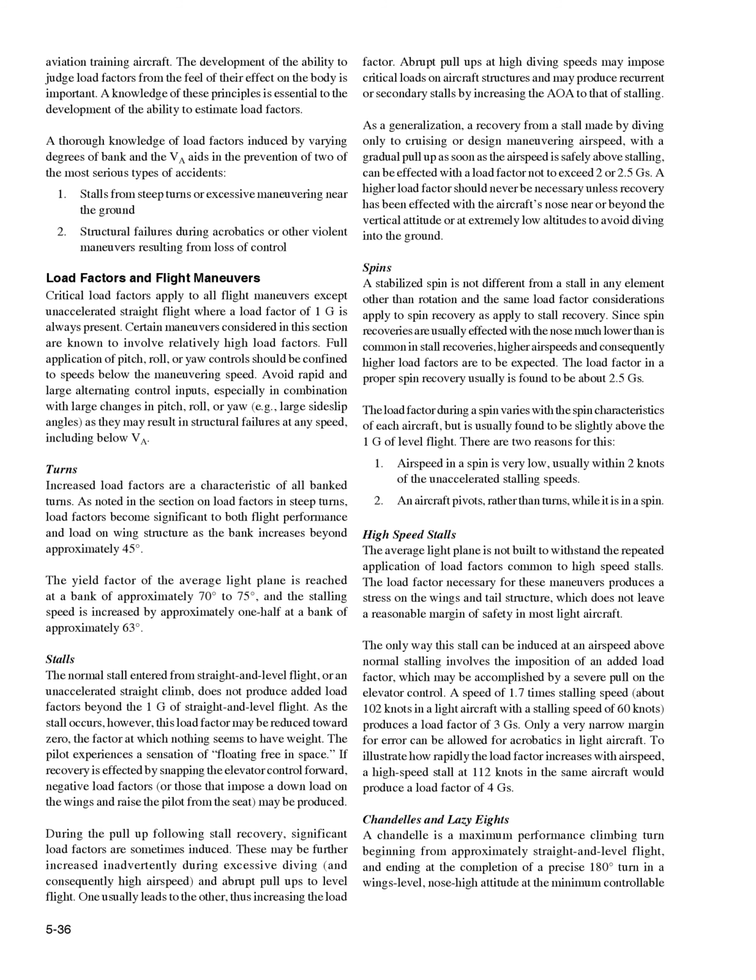A speed of 1.7 times stalling speed, about 102 knots in a light aircraft with a stalling speed of 60 knots, produces a load factor of 3 Gs. Only a very narrow margin for error can be allowed for acrobatics in light aircraft. To illustrate how rapidly the load factor increases with airspeed, a high-speed stall at 112 knots in the same aircraft would produce a load factor of 4 Gs.